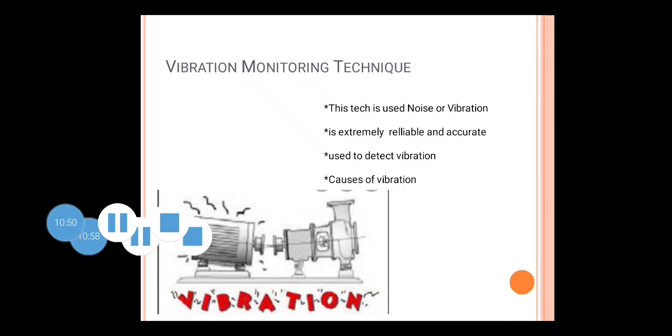Bad gearing, noise may exist. Mechanical looseness, nuts and bolts, parts damages can occur. Bad conditions of the belts and reciprocating forces may exist, and because of those reasons vibration may exist.